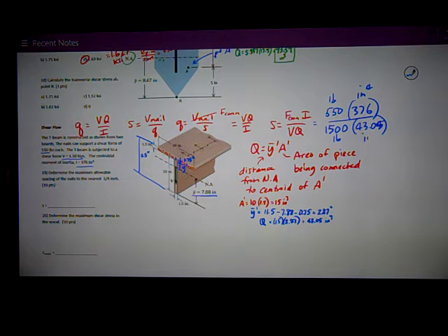That's inches cubed. So I got pound inches to the fourth on the top, pound inches cubed on the bottom. Pounds cancel out, inches to the fourth cancels out all but one. So I'm left with inches as the unit of my answer, which is what I want because it's a spacing. I run the numbers and I get S is equal to 3.2 inches.